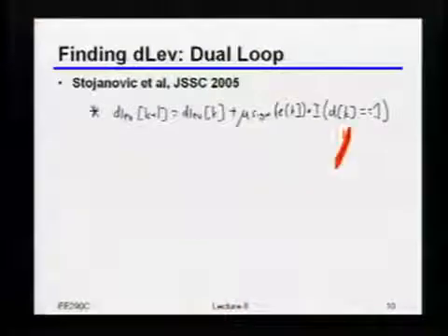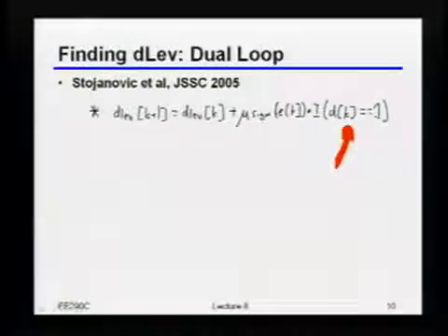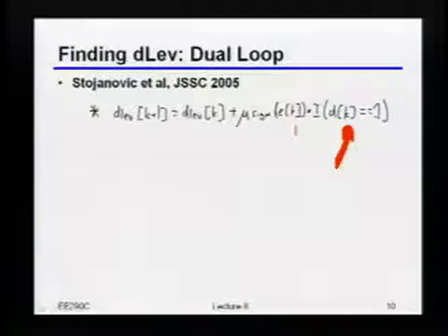The only caveat is that when I did this, I only had my updates when my data was actually a 1. So if I had really bad bit error rate and I was getting a lot of zeros when my data was a 1, then maybe it wouldn't converge. But the good news is, I need to be making mistakes about half of the time to not go in the right direction. My dither might be horrible, but to really not go in the right direction is pretty tough. I'm sure you can come up with conditions where it would not converge, but for all practical purposes, if your link was going to work, it'll converge. But those are both great questions.